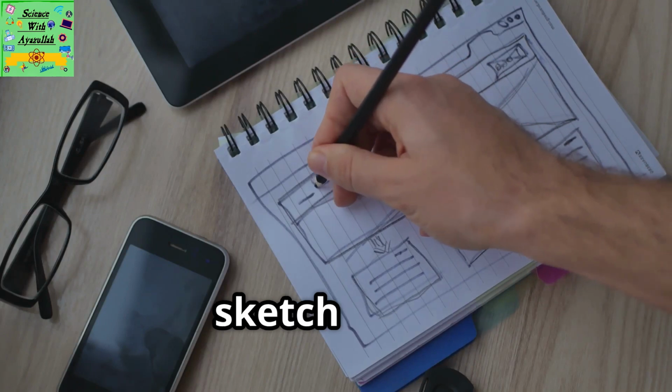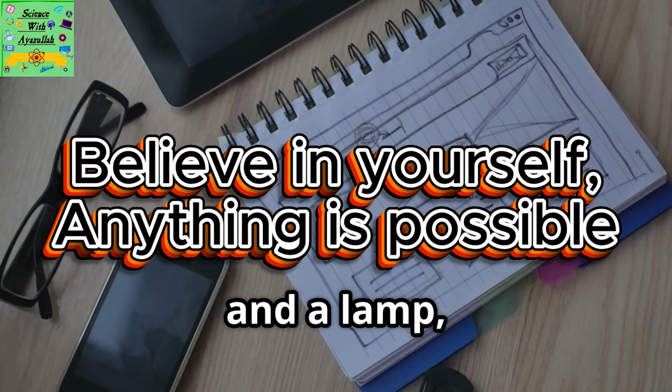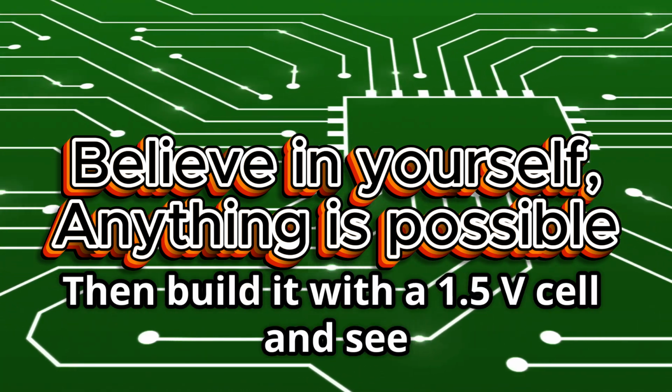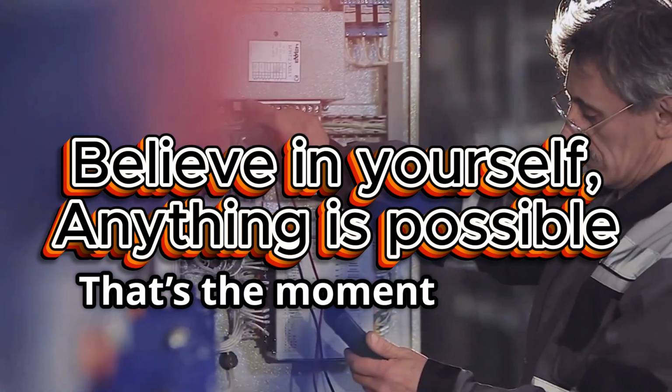Grab a notebook, sketch a cell, a switch, and a lamp, and make your first diagram. Then build it with a 1.5 V cell and see the mapping come to life. That's the moment circuits click.